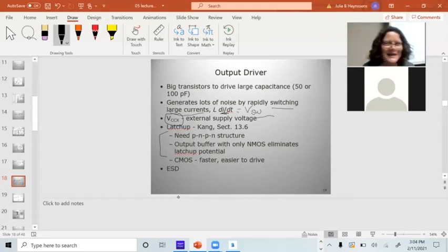And he gets them up to the lab, and the threshold voltages don't match. The hit wasn't enough to blow them, but it was enough to do ESD damage. Low-level ESD damage raises the threshold voltage of devices. Sharber should have stopped him at that moment.